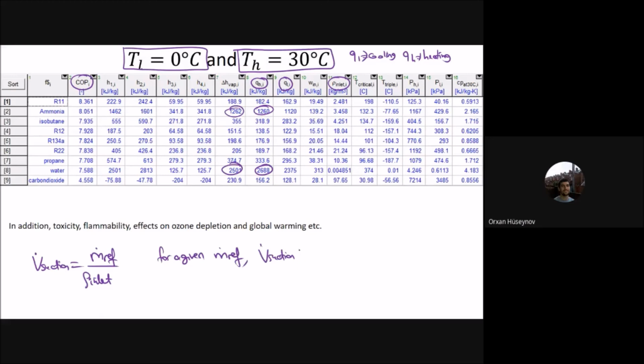so this one becomes high for low density. Okay. If this one is high, then what we want at the end is the volumetric efficiency. If you remember, it was V dot suction divided by V dot displaced. If the suction flow rate is high and you want higher efficiency, then this one should be high too.